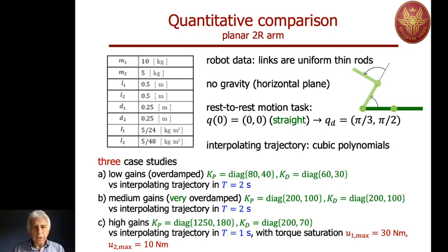If we choose an interpolating trajectory instead of a constant reference QD, and we choose as target motion 1 millisecond, of course this will bring no benefit because we are moving instantaneously from the initial configuration to the desired one, and this is like having a step response. So we should allow enough time, and this is also a choice that is based on the actual dynamics, so the information that we have about the robots. So here we choose 2 seconds for doing this motion.